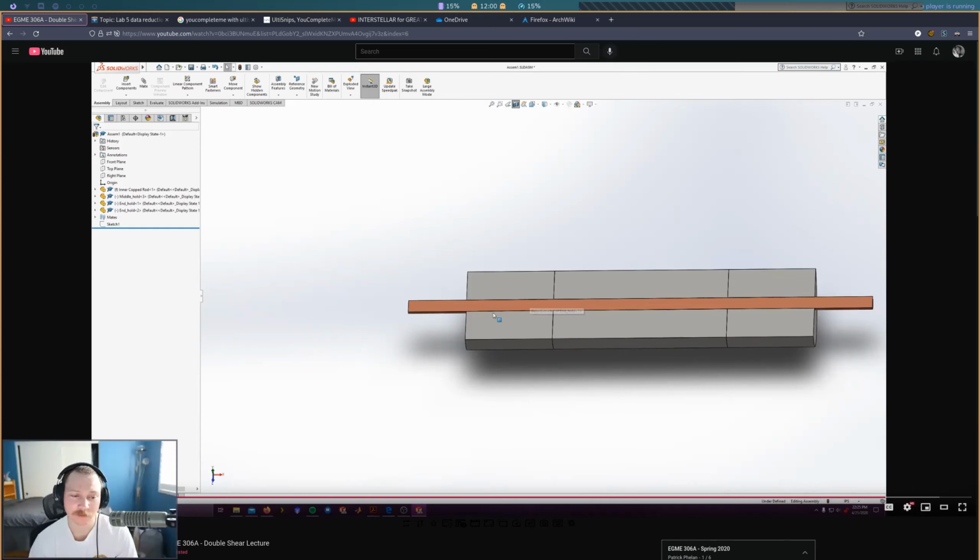It's pretty basic. We're just looking at the shear stress, double shear, and we're looking at the bearing stress. We'll make a plot for the shear stress versus the crosshead position for all 3 materials. We're going to have 2 trials, so we're going to have two graphs, each graph with 3 curves on it. Compare the theoretical shear stress to the experimental shear stress. Keep in mind the theoretical formulas are very crude approximations, and we'll calculate the bearing stress as well. So that's what you're going to be doing for the memo, and that's it for today.